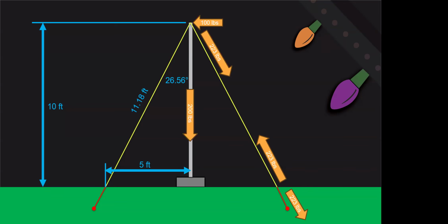You want them snug. Just like anything you see when you're assembling anything, don't over tighten. Over tightening is always bad, and the reason here is you're putting too much load on it. Also, as you're pulling down farther, if you over tighten, you're starting to pull your anchor out of the ground. And now your anchor can't hold up your tree when the wind blows because you've already pre-tensioned that.